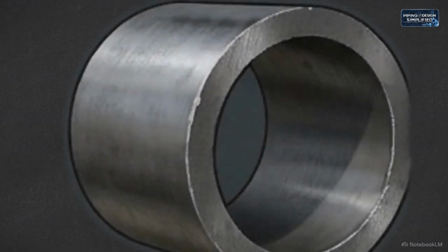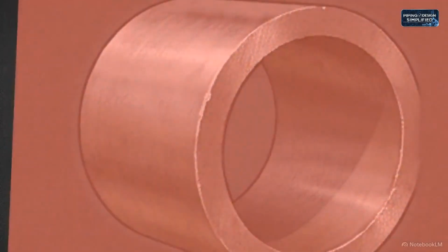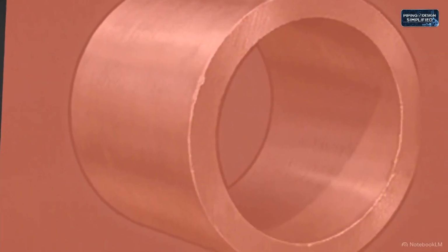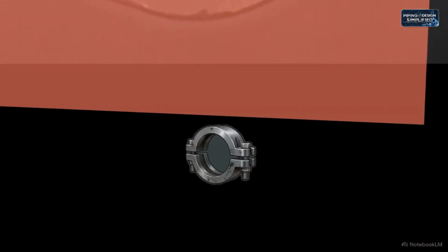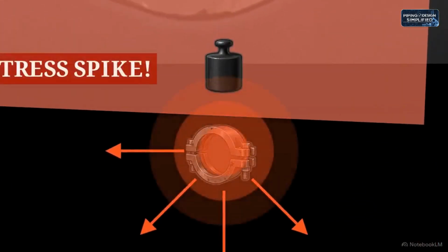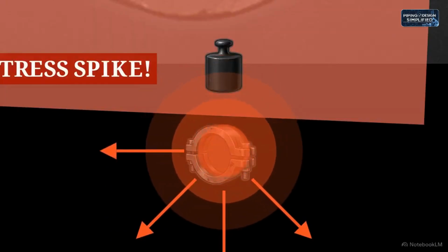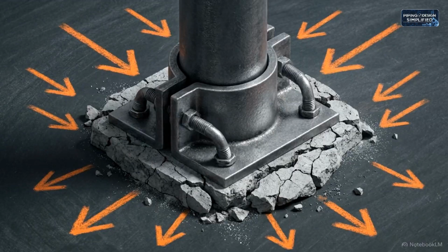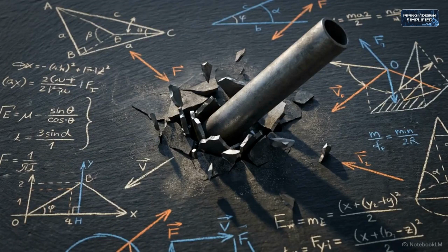The danger of liftoff is that the dead weight of the pipe hasn't disappeared. The Y+ support is now mathematically inactive. As a result, that heavy sustained load immediately drops onto the nearest fixed anchor, causing the local stress levels to spike. This abruptly transferred deadweight load attacks the rigid anchor, which was likely never designed to hold the combined weight of the entire span. This specific scenario is a primary cause of structural failure in high-temperature systems.